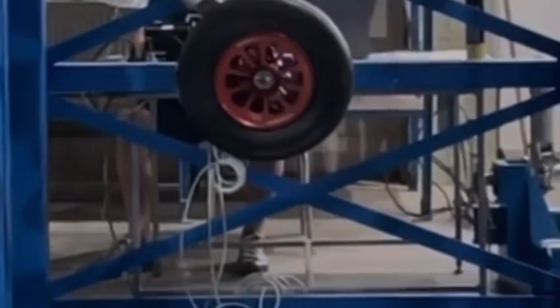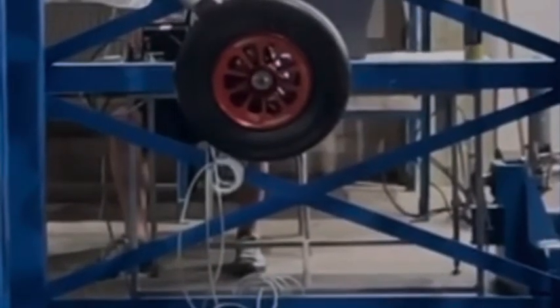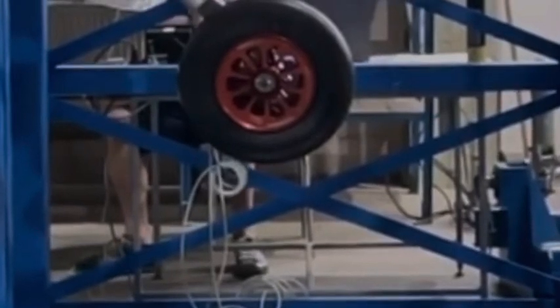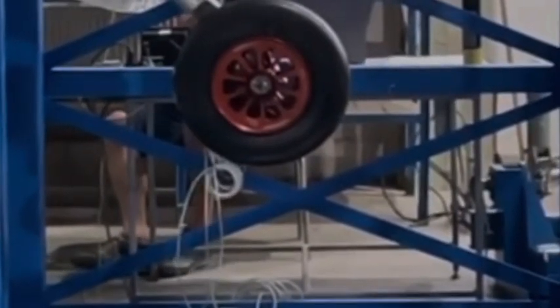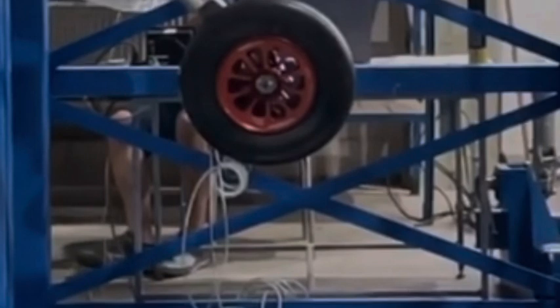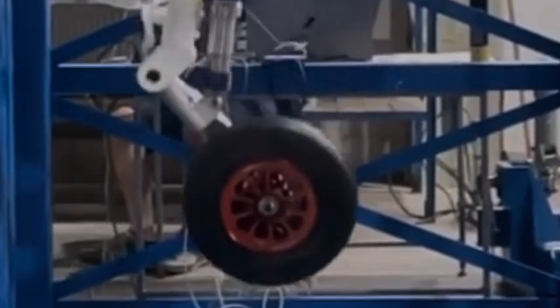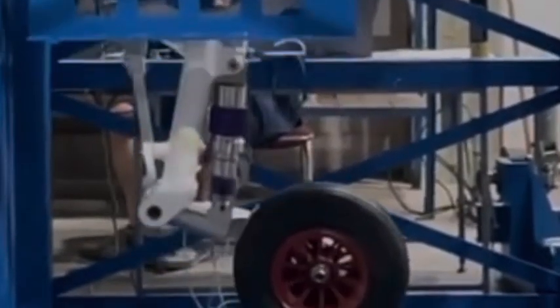When a landing gear is designed, before it is released for service or attached to the fuselage or wing of an aircraft, different tests should be performed on it, so the manufacturer can make sure that the landing gears are capable of absorbing different shocks and stresses without being damaged or deformed. One main test performed on the landing gear is the drop test.